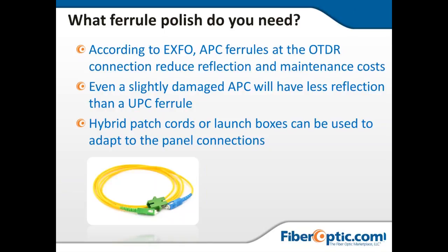The difference is that the APC connector is an angled ferrule, with an 8-degree angle to reduce back reflections on systems like fiber to the home systems that are maybe using 1550 for their RF signal, their video signal, and that has a lot of reflections that come back, and the reflections cause a lot of bit error rate problems at the 1550 wavelengths.